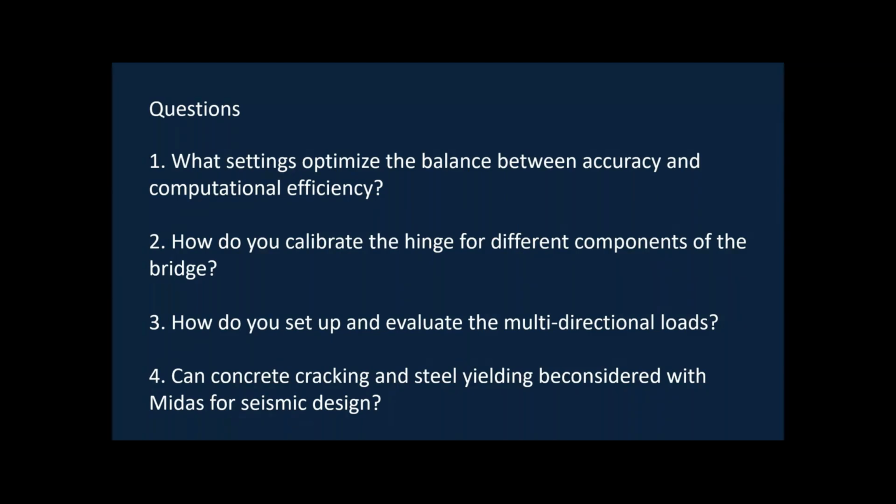So addressing the second question, how do you calibrate the hinge for different components of the bridge? The calibration of the hinge data is completely based on the type of the hinge that you are defining. If you are using the concrete section, then we shall choose a plastic hinge model in such a way that the degradation in the concrete, that is the stiffness degradation, as well as the pinching effects in the concrete are accurately considered in the plastic hinge data.